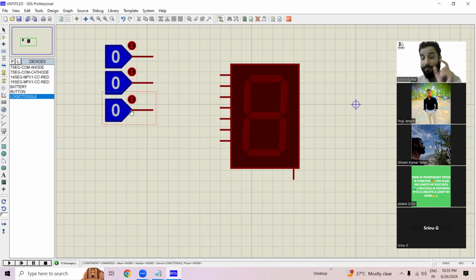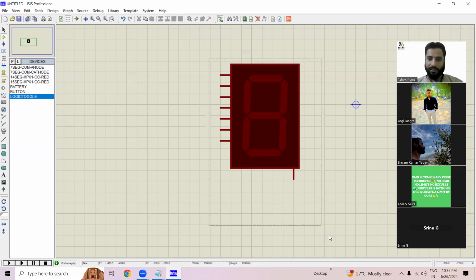So when we connect a 7-segment display, at least 7 pins are required. If our controller has only 14 pins, that means 7 pins are required for the 7 segments, and the remaining 7 we can connect with other components. And if it is not possible to connect all the components with the remaining 7 pins, we need to change the controller from 14 pins to 20 pins. That means we have to purchase a bigger controller, which will increase the cost as well as the size of your circuit. So at that time I suggest using an IC.